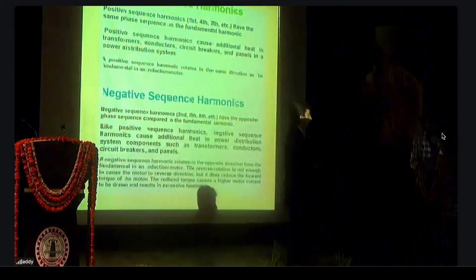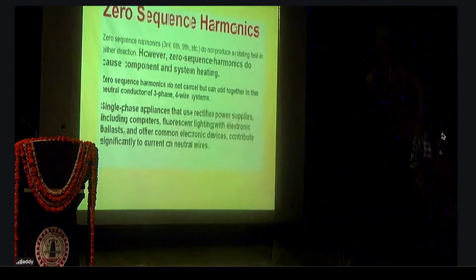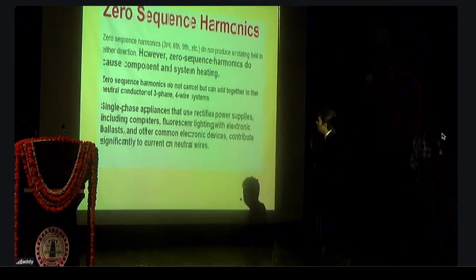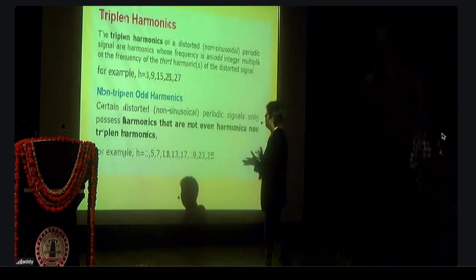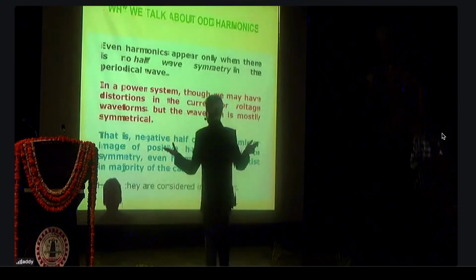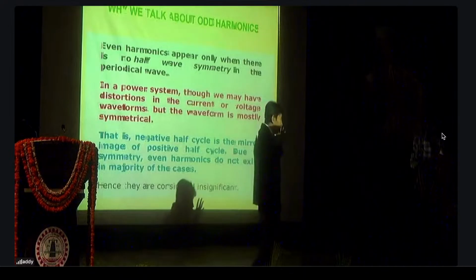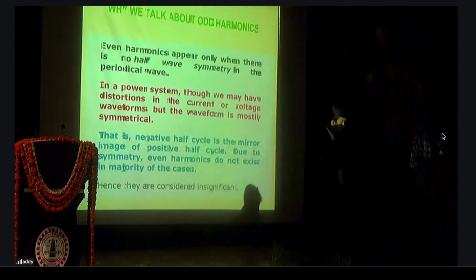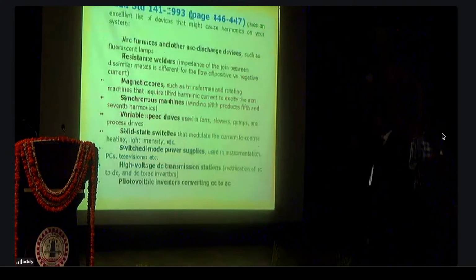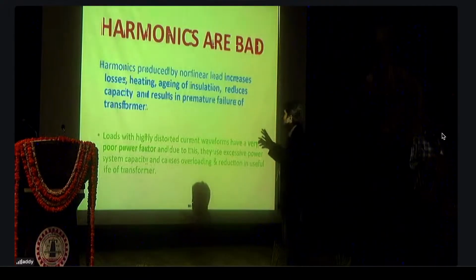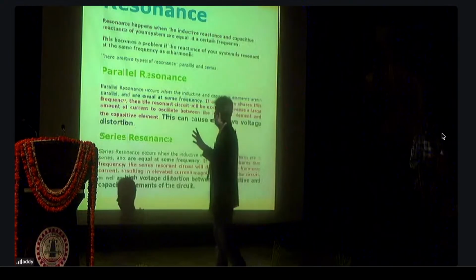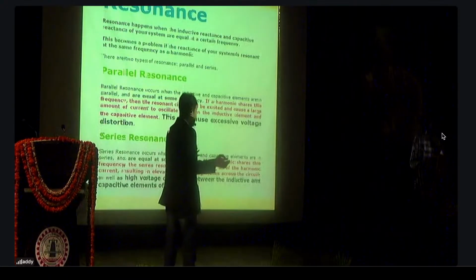And this is the IEEE 519 standard to be taken care of. You have to understand the zero sequence impedance and triplen harmonics. We have to take care of the harmonics related to your equipment. You have to follow IEEE 141 that talks about what the impact is. Next. Resonance that may be there.